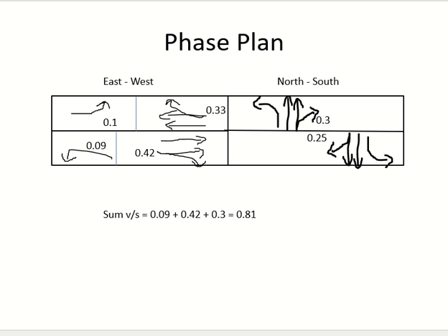Okay. So in the previous example, we discussed the trials. Put all the movements of one side together, then put the movements which have the same V by S ratio together, and so on and so forth. Here we have the advantage in the north side direction that the left turning doesn't require a phase. We said it is permissive. So in that case, we can let them go together. There is no problem, because right turning is already permissive, and left turning also is permissive.